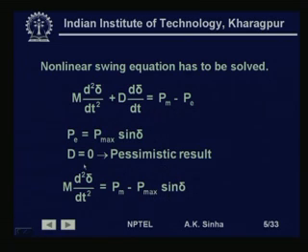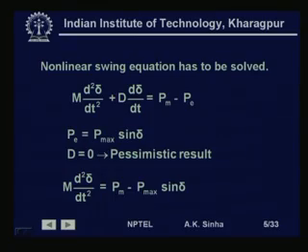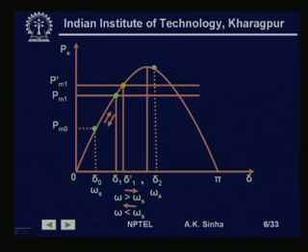So, when d is equal to 0, we are going to get sustained oscillation, which means the system is going to have oscillations all the time. Of course, that will not be the case because in an actual system there will be d. So, taking d is equal to 0 basically leads to a pessimistic result. Now, let us see how this whole dynamic process takes place.